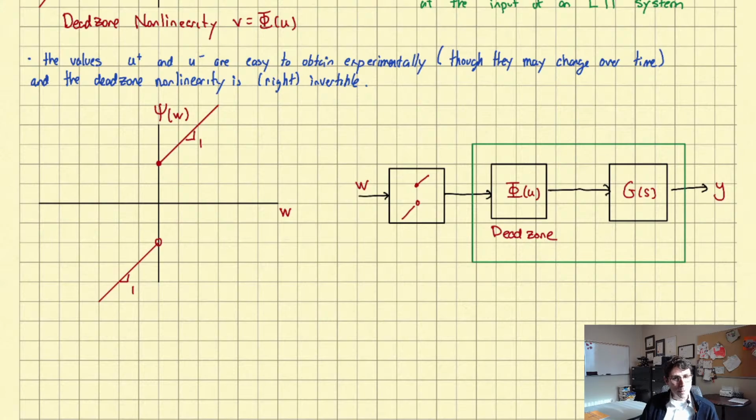And of course, this leads back to the drawback of this approach that I mentioned at the start of this lecture. The drawback is that if this is not a good model of the nonlinearity, then this will not be a good cancellation, and your closed loop system will not appear to be linear. Again, I'll reiterate what I said at the start of lecture. Cancellation is nice because it doesn't require approximation, so in principle you could get larger regions where this controller will work.